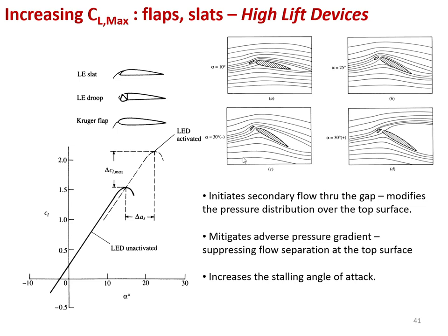So essentially what happens with these types of mechanisms is that they are either going to increase the camber, as you can see, or they are going to control the flow. So two different mechanisms. Let's look at this example of a leading edge flap that separates from your body and can move.